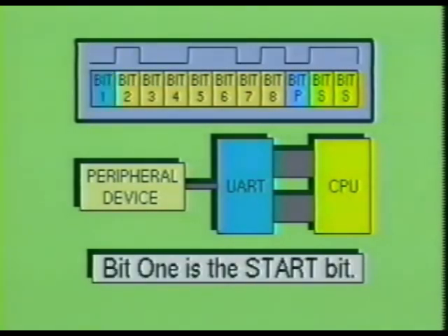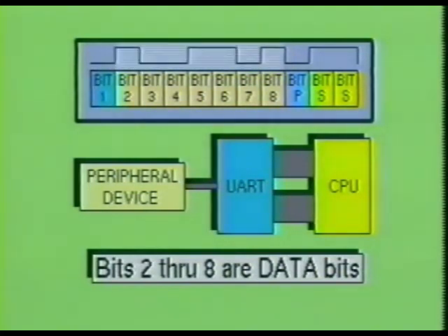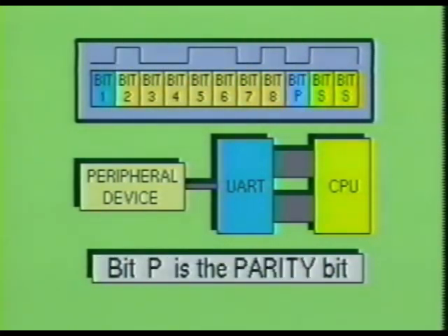Since the serial input or serial output is held at a high impedance state, they must be brought low to start the transmitting or receiving of data. Therefore, the first bit in the transmitted data will always be a low bit. The low start bit is then followed by the data contained in the data bit group. The next bit following the data information is the parity bit. If this bit is high, then even parity is used. If this bit is low, odd parity is used.